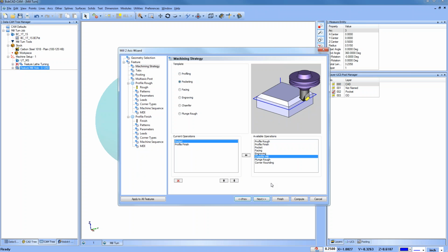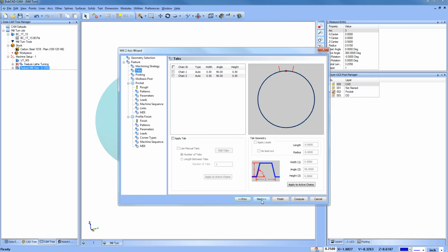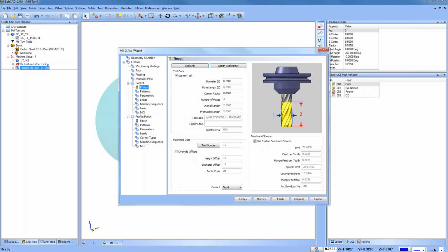Actually, I'm going to do the chamfer routine separately because I want to break the edge on the pocket wall and the circle at the same time. And sometimes I find it's easier when you just separate them. But again, that's up to you.